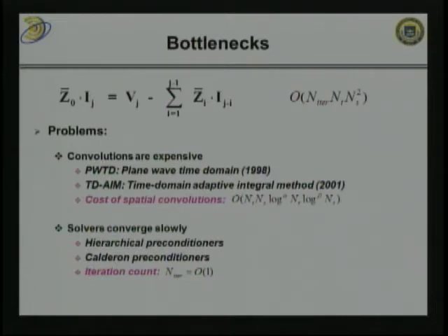By this we mean that the ratio between the largest singular value and smallest singular value is very large. And this means that if you solve this thing iteratively, by first making a guess for Ij and then correcting it by multiplying over and over that matrix by trial vectors Ij, it turns out that procedure converges extremely slowly, especially when the geometry that you're analyzing has many small multi-scale features and things like that, which is, of course, exactly what engineers these days are interested in.